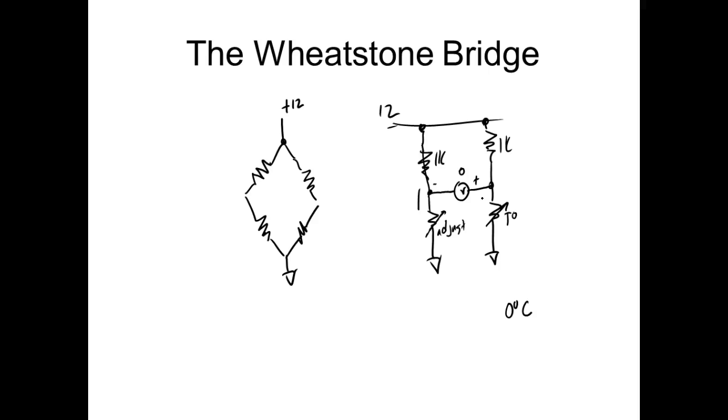Set a 0 reference. So I've got a scale out there. This scale's got a weigh bridge on there. That weigh bridge weighs 15,000 pounds, right? You understand? But I want to make the weigh bridge equal to what? 0. So we had a 0 adjust on there, and we adjust them out until it measures 0.